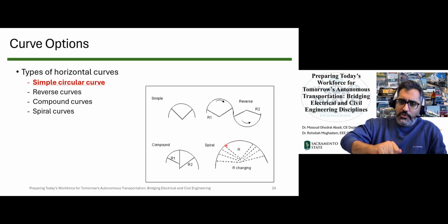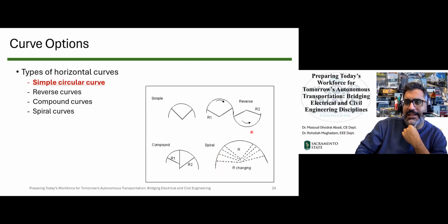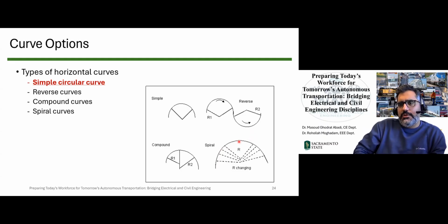When you're usually driving, navigating the turns, horizontal curves, it's been shown that drivers pick various radius as they are going through the curve. So if we want to design exactly similar to the way that drivers drive, that would be most close to a spiral curve, which means varying radius for these circular curves.